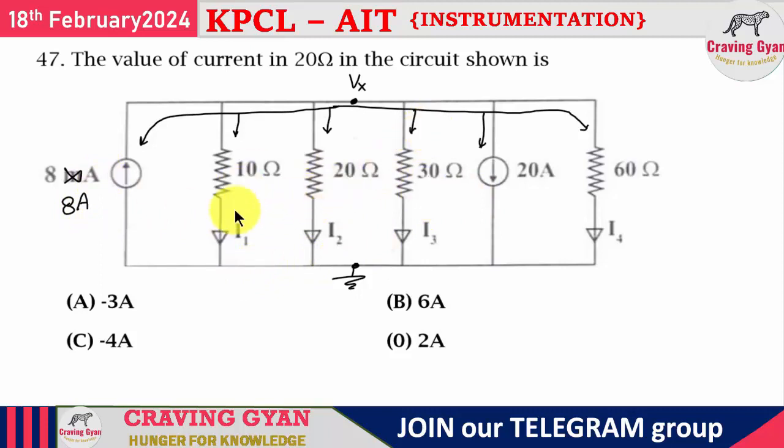So I am going to take this 8 milli as 8 amperes and then solve. The outward current on the left one is minus 8 amperes, since the left one is in the opposite direction. So it is minus 8 plus the current through the 10 ohm resistor, that is (Vx minus 0) divided by 10, plus Vx divided by 20, plus Vx divided by 30. The current direction and the current that is flowing are in the same path only, so I take it as plus 20 plus Vx divided by 60, which equals 0.